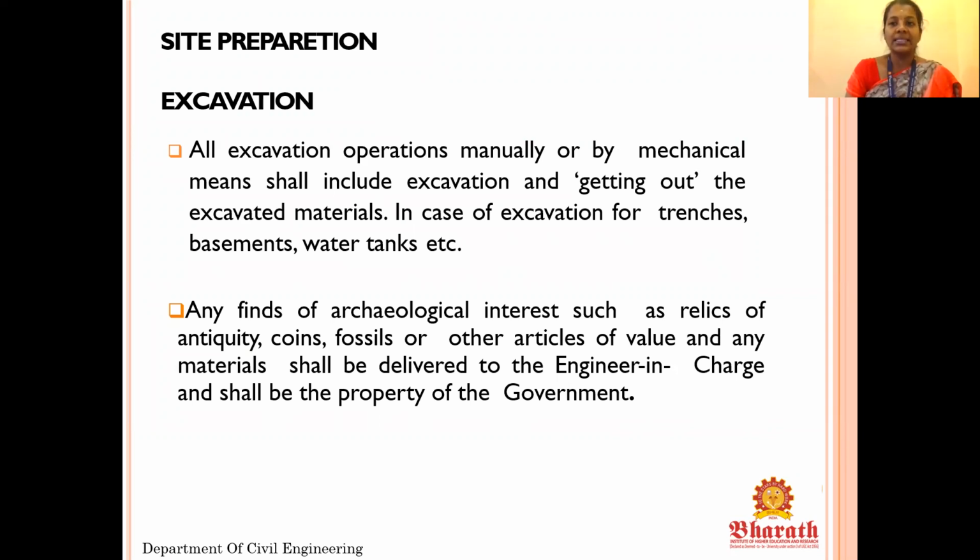Now, after clearing, the site has to be prepared for the construction work. Before doing the excavation work, we have to prepare the plan, in which the arrangement for placing the site office, storeroom, labor quarters, medical aid center, and godowns for keeping the construction material and other facilities is properly prepared. Everything has to be placed on the site so that it will be helpful for the storage of materials and also for labor residential purposes.